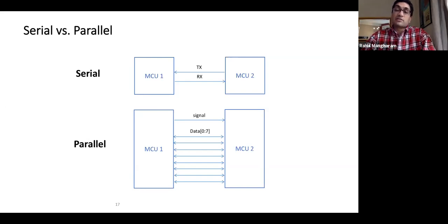So the yield goes down, and therefore you want to have smaller die sizes, and therefore you want to have fewer IO lines, because the IO lines have a minimum size that you need to have to prevent crosstalk from happening. And also, the more lines you have, it just means that you need to have more senders and receivers pushing out the energy from these lines, right? So you need to power on more of these pins over here.